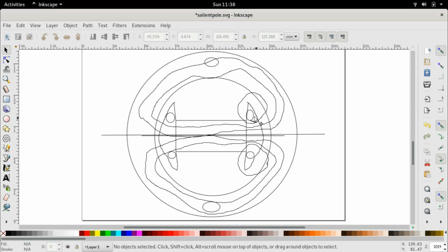And once again, we can make the approximation that the high permeability segments through the rotor and the stator can be neglected and consider only the air gap instead. And as you can see, since we are considering only the rotor flux because of the excitation of the rotor, it is very clear that this air gap is not changing.